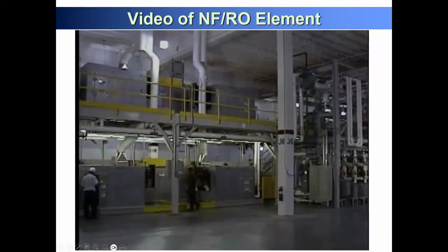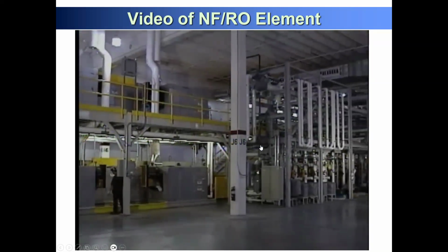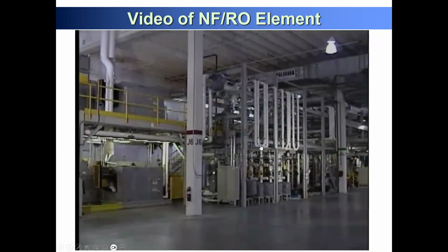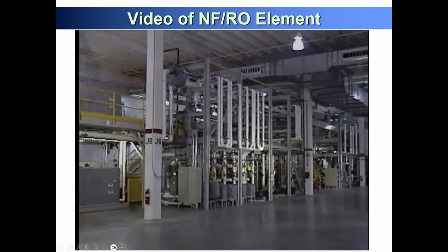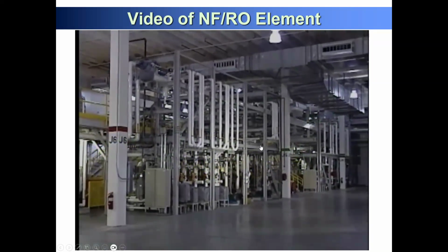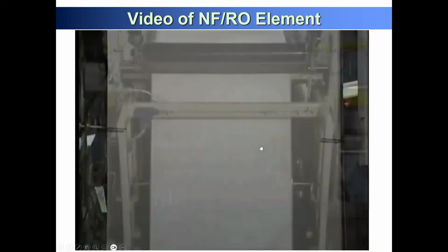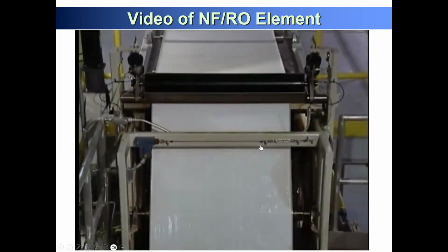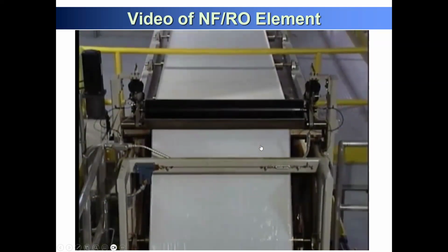With each new generation of manufacturing equipment, the quality of FilmTech membranes is continuously improved through advanced process automation and control, from handling polyester-based material through casting the microporous polysulfone support to the complex polymerization reaction that creates the polyamide membrane layer.